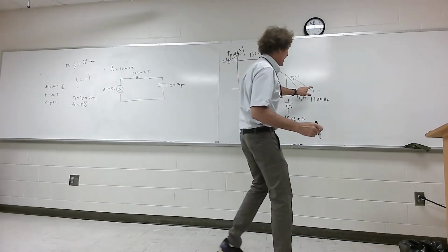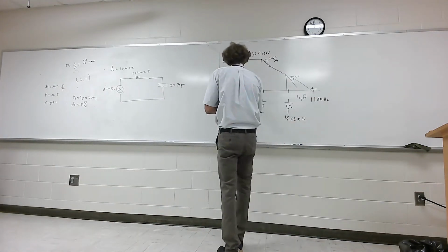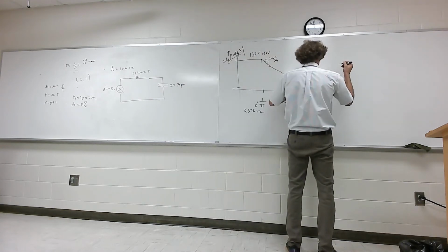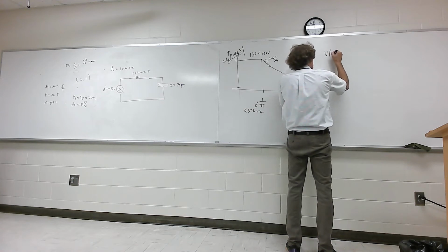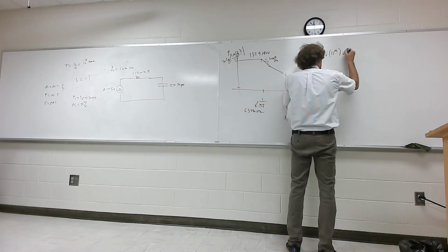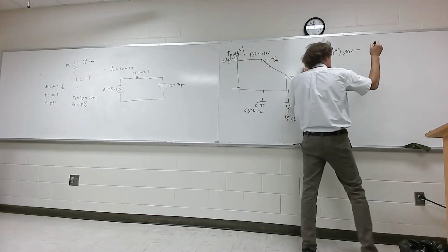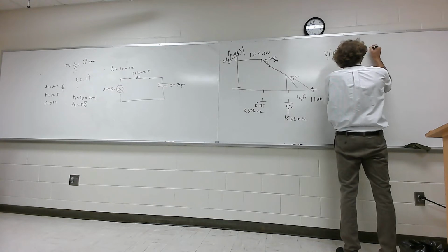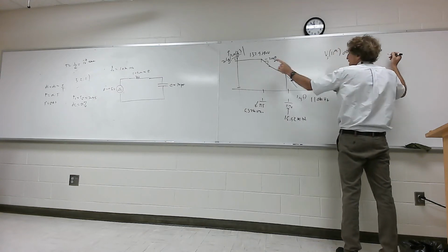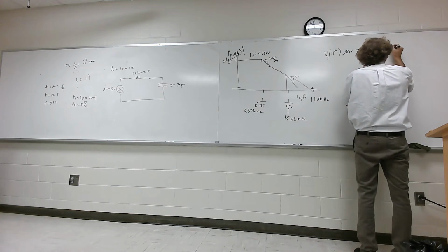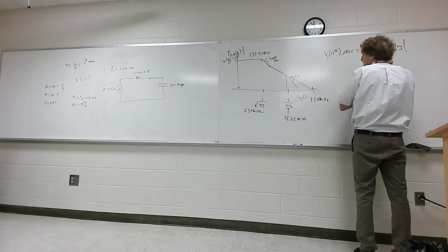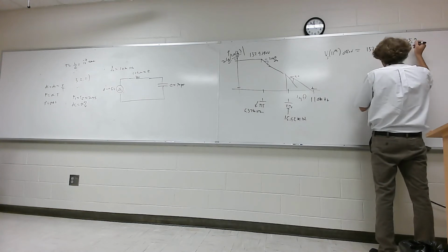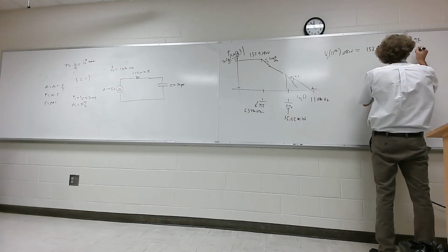So now to get the value out here, way out at 110 megahertz, we start by saying this value of the 11th, I'll just put 11, in dB microvolts of the source, is going to be equal to that 133.9. That's the value it starts with. Then minus 20 times the log of the upper frequency, which is 15.92, over the lower frequency, which is 6.37.